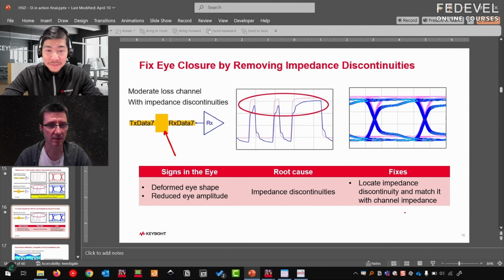So basically, this means exactly what we mentioned at the beginning. For example, when you are routing traces on your PCB, the traces should always have 50 ohms. Even if you are changing layers, you should try to keep it always 50 ohms, and then the quality of the signal will be the best. You need to have a controlled impedance line. And I think you have a simulation where we can actually have a look and see the reality.